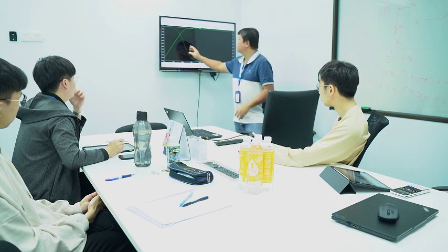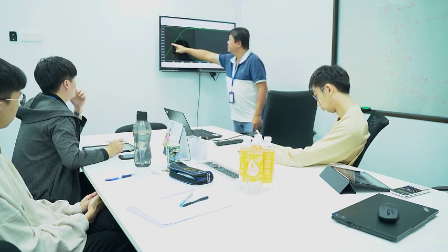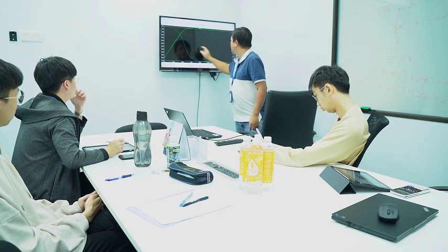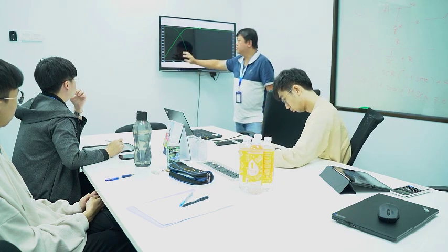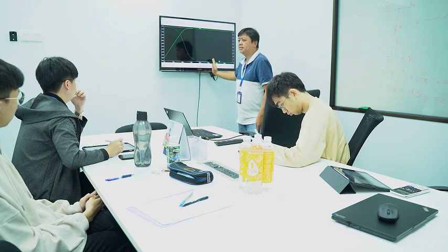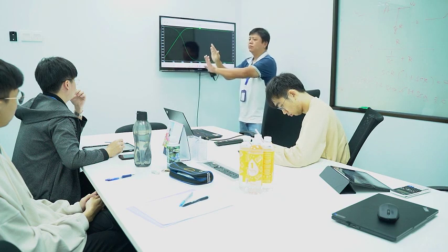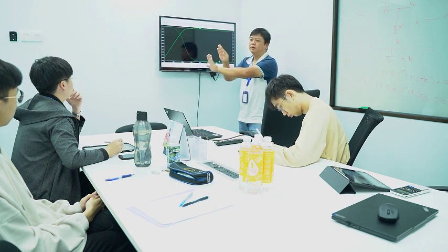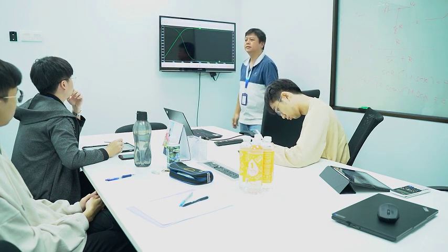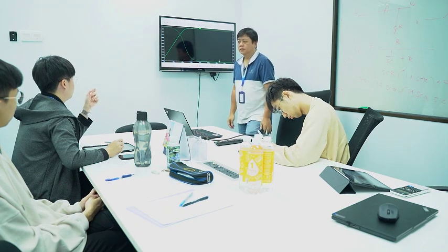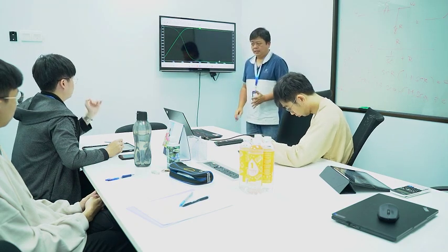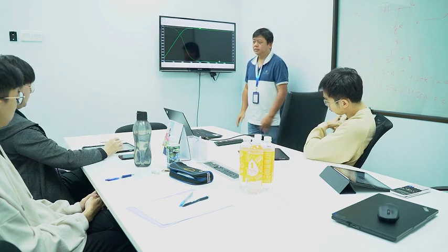For example, in this case, if you operate at 10 Hz, your phase shift will be 36 degrees. As you increase the input frequency, your phase shift becomes lesser and lesser. At the end of the day, input and output just overlap one another. So when it approaches the cutoff frequency, the phase shift gets lesser and lesser. Okay, understand.